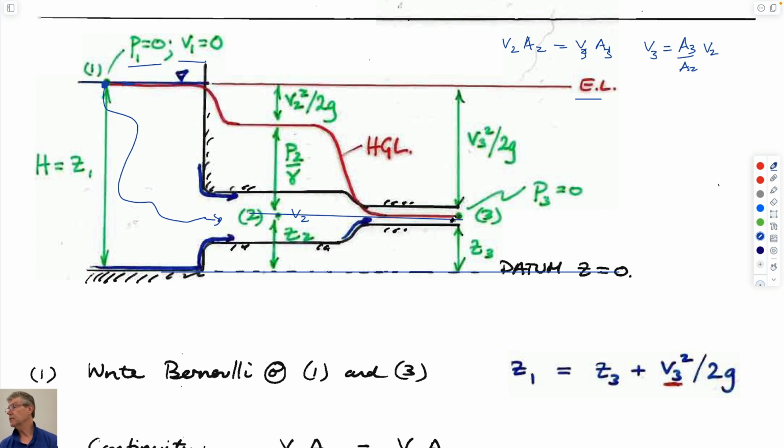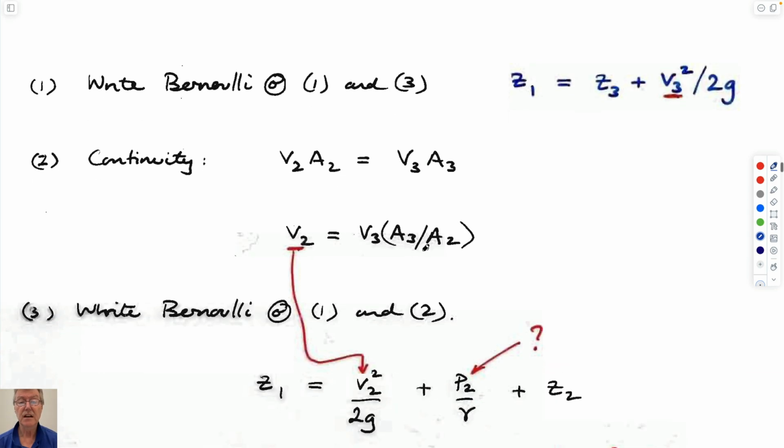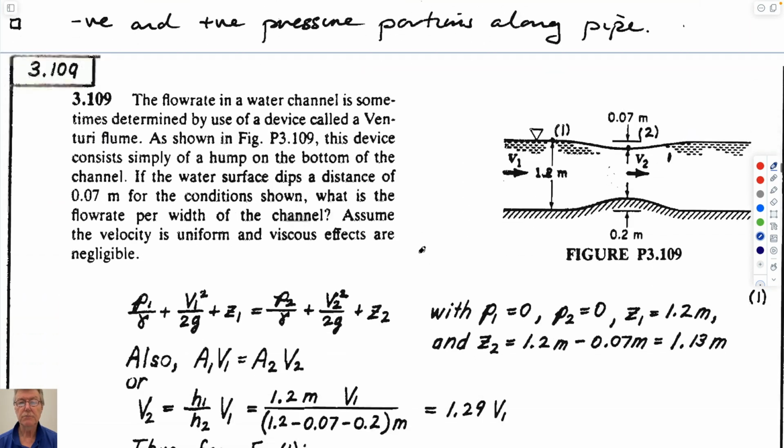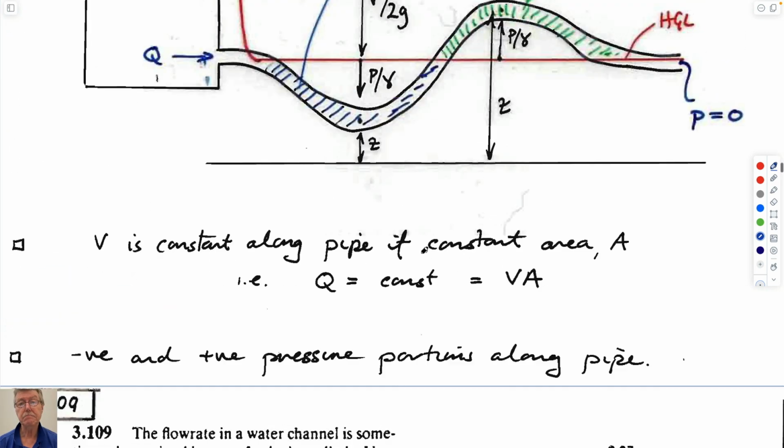But what's going to happen to pressure? Pressure is going to be reduced. How much is it going to reduce? If it's coming out here, then by definition the pressure at 3 has to be 0, atmospheric. And so we mean that we've completely shut down the pressure. Pressure is an infinitesimally thin line for the pressure head here, and it's completely dominated by the velocity head and the elevation head. And so that's it. So that's the best explanation I can provide for what we've talked about.